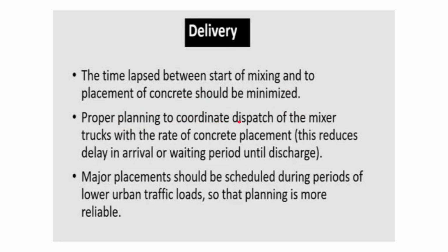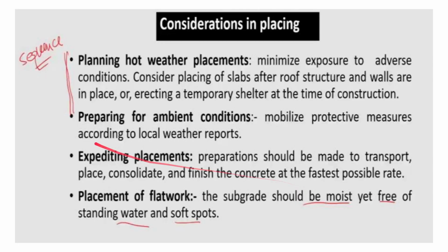Proper planning to coordinate dispatch of the mixer trucks with the rate of concrete placement is also required, so that firstly the process is efficient, and secondly this reduces the delay in arrival or waiting period until discharge, because the more the delay, the higher the chance of the temperature getting higher. Major placement should be scheduled during periods of lower urban traffic loads, so that planning is more reliable, because otherwise it will be congested, and there is a chance of increasing the temperature or direct contact with the sun. So these are some of the considerations in terms of delivery.